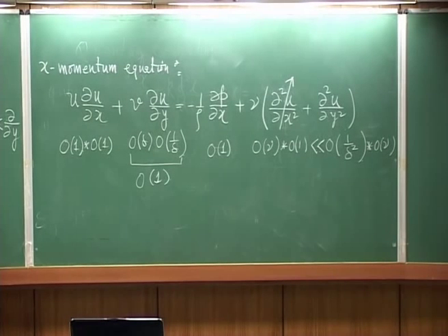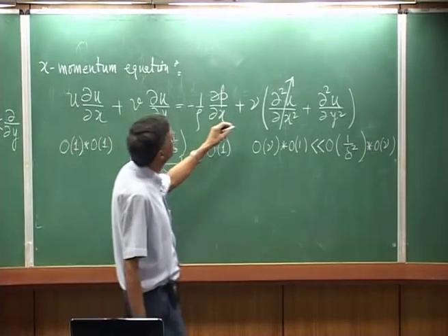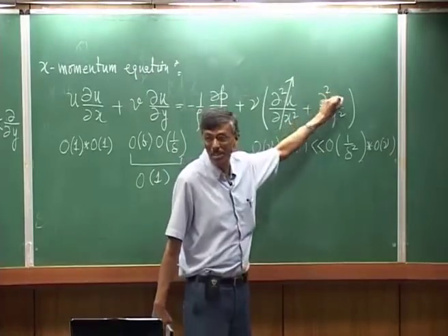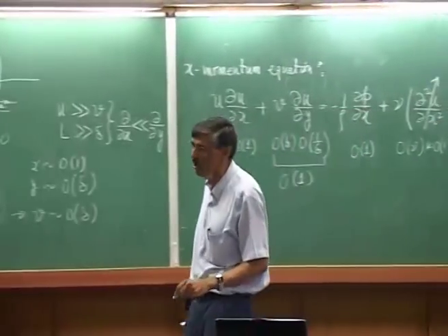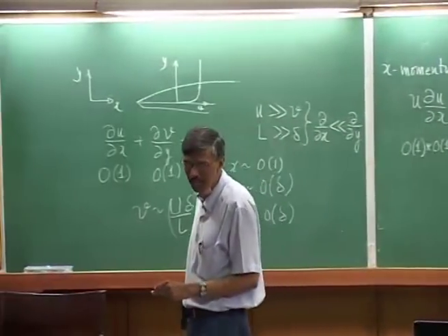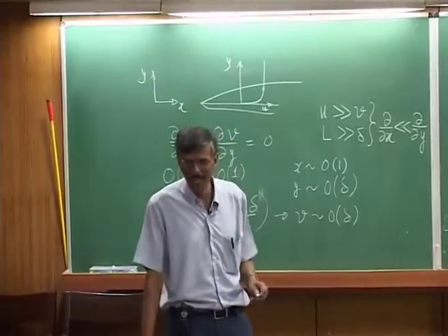So, that is why in that spring mass system we could not make that naive operation of m going to 0 and dropping the highest derivative term, then we were unable to satisfy the initial conditions. The same thing here, the nu is multiplied with the highest derivative term, the diffusion operator. And so, we cannot just simply wish away.